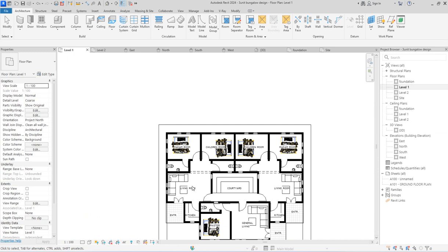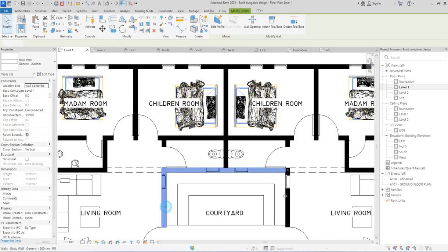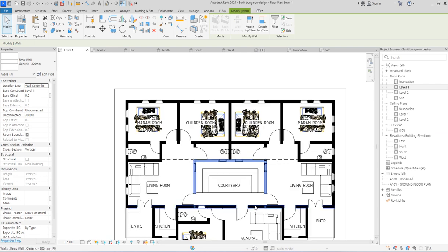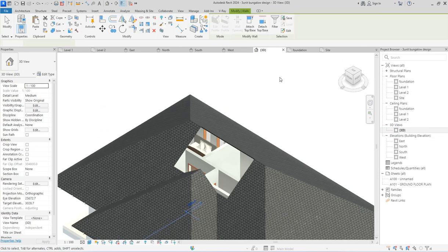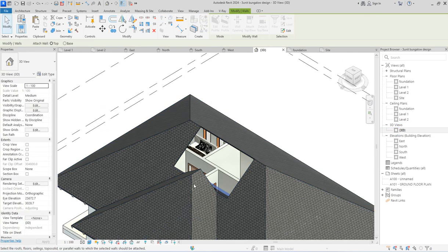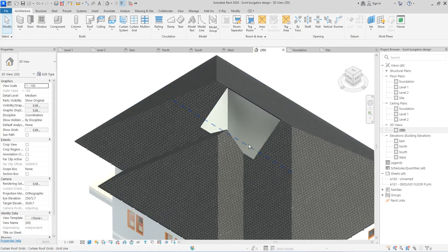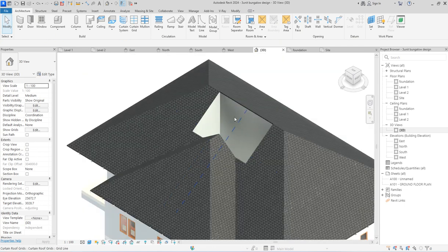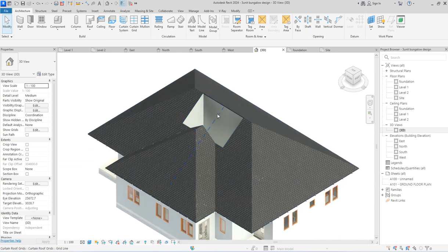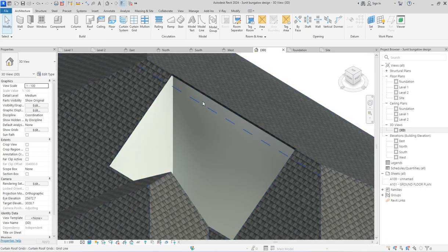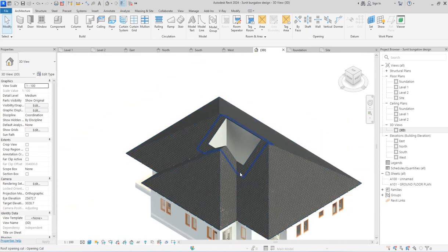So you go back to the foundation, select all these four walls. So you go to 3D and you say you should attach to the roof. So you say attach to this one. So you don't see any inner partition any longer. So this one is covered up. So you can now start to be working on the layer of the one that has the ridge cap.